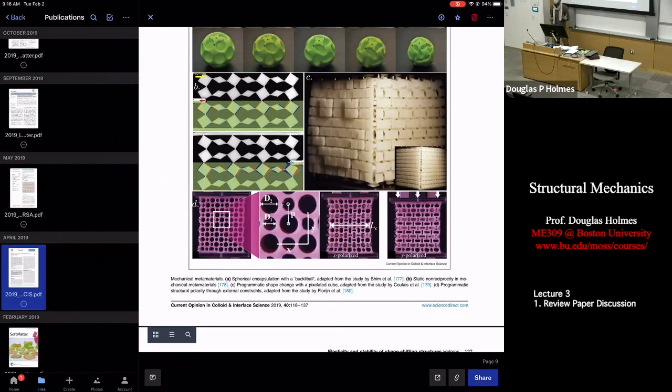That's one of the benefits to learning this stuff that I feel goes undersaid: as long as you understand the relevant energies at play, you can scale them accordingly. What I mean by that is, at the beginning of the paper, we talk about the elastogravity length scale. So at what scale does gravity start to matter? That's something you have to keep in mind if you're scaling it up. It's like, okay, is gravity going to start to deform this? Maybe I need to make it stiffer here. But these things can, in general, scale massively.